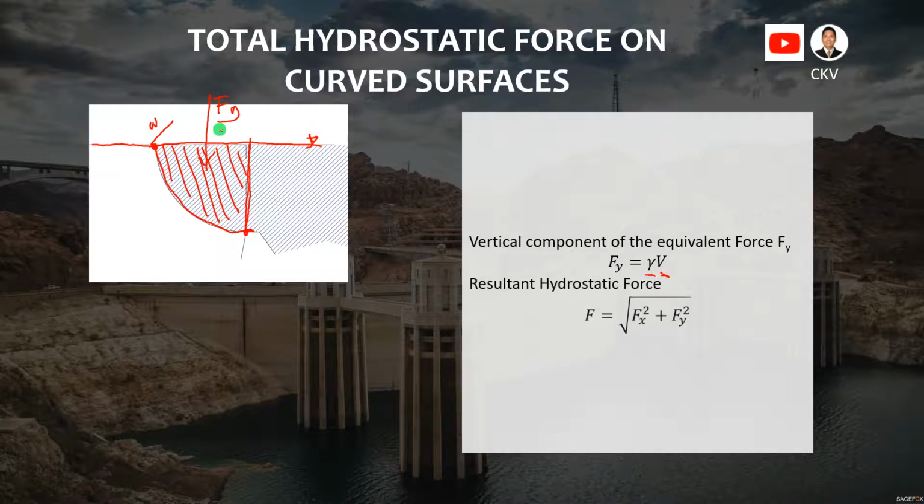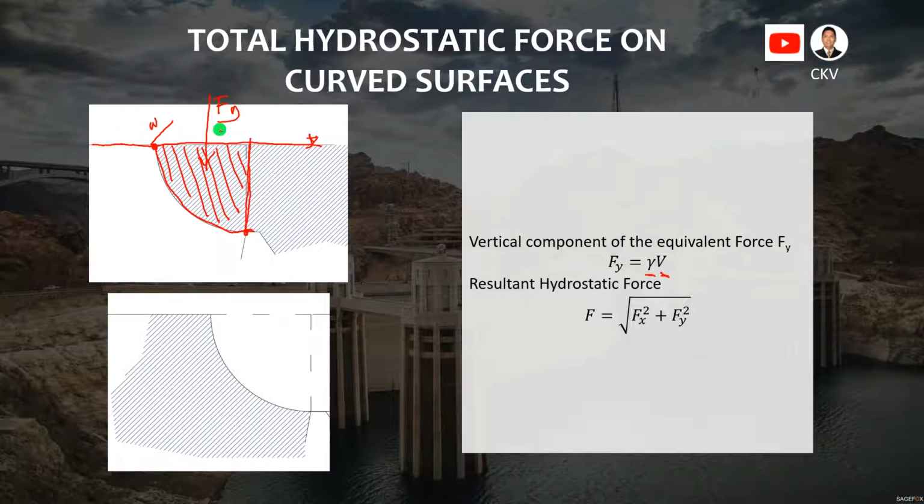Before we determine the hydrostatic force for the vertical force, we have two cases here. The first one is where the water is above the curved surface. When we extend both edges of the gate, it is filled with the liquid.